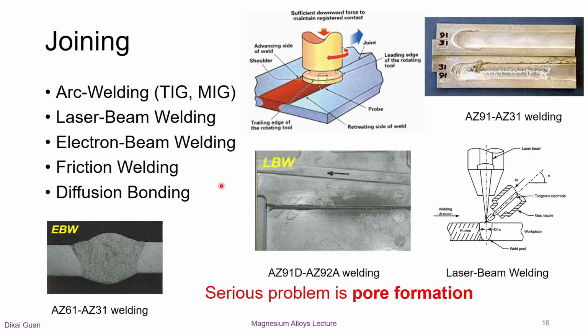Magnesium poses high demands on the welding process because of its physical properties. Magnesium alloys show a relatively broad melting interval of about 420 to 620 Celsius degrees. In combination with low melting eutectics, the risk of hot cracking needs to be taken into account.